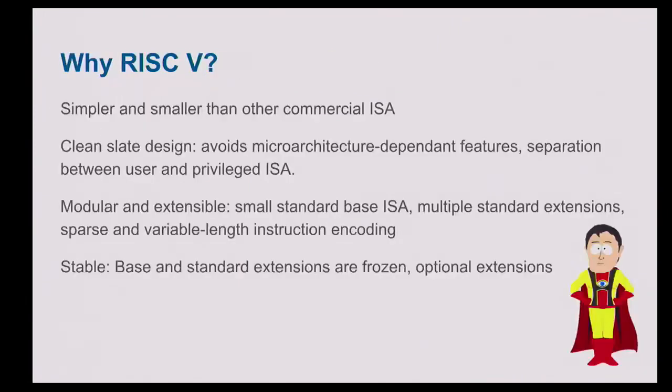Why is RISC-V important? Well, because it is simple enough and small enough to be presented, for example, in classes, and it is simpler and smaller than any other commercial ISA. It's a clean slate design, so it doesn't have the burden of some legacy architecture it needs to be compatible with, and it clearly separates between privileged and user mode.